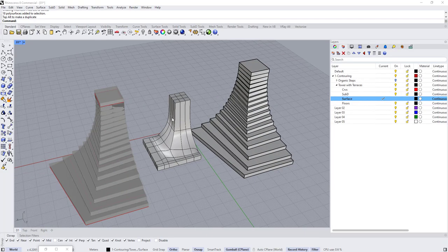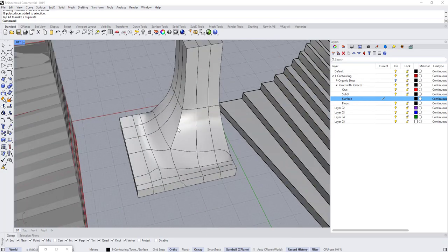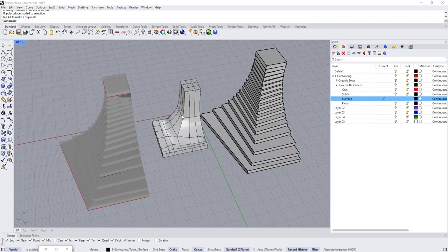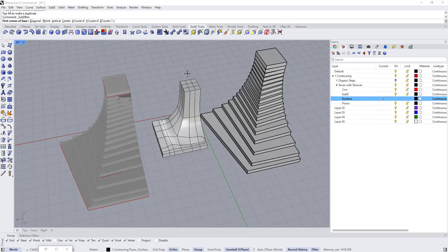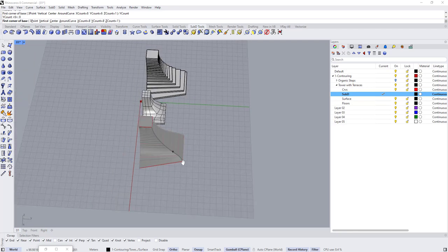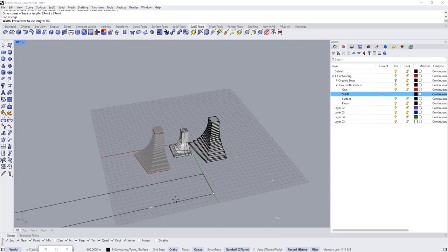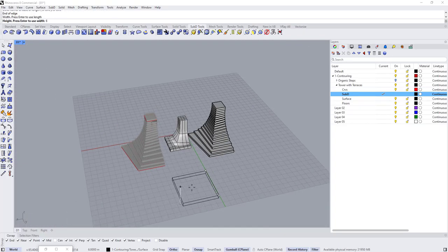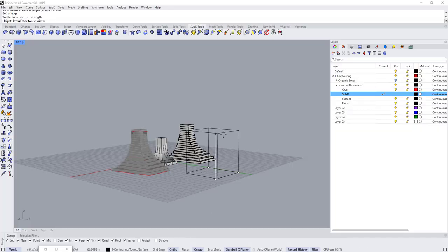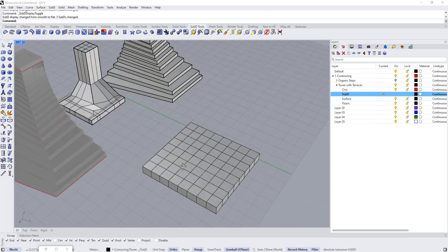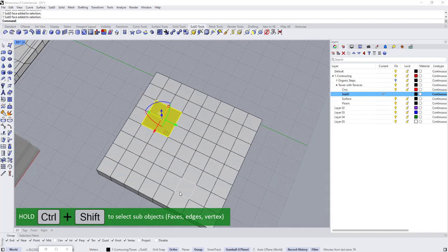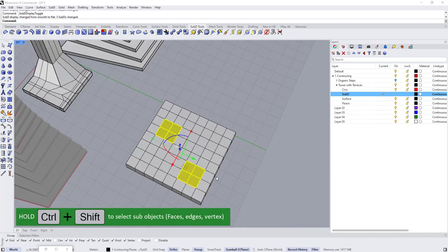By the way, we can create a lot of shapes way more dynamic using SubD. So I want to show you something else. So let's come here and choose SubD box, make it maybe 8 and 8. SubD layer. Let's draw the SubD here, 3 point, make it maybe 60 by 60, and the height of 6 meters. Negative 6. Oh. So if we come here, maybe select, maybe we're going to create some kind of a tower with.